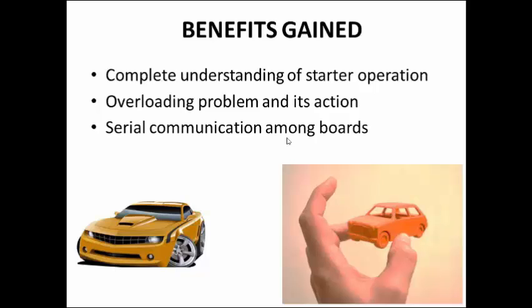To the master board we interfaced the LCD display and the switch. We left the slave board to do the operation of starting the DC motor on receiving a message from the master board. And finally, the impact of grounding also hurt us while implementing the project, because two different boards come with two different potentials. So the impact of common grounding also played a major part.